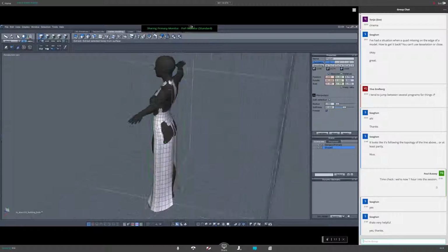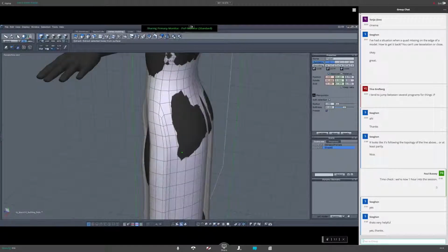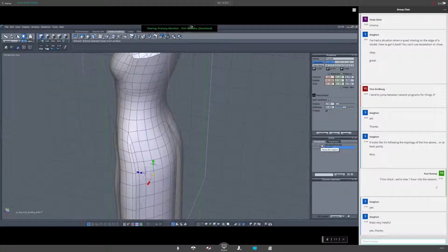And how do you do this without going crazy? Of course, symmetry is your friend. Select one of these offending polygons which have disappeared inside your figure and then use something called soft selection here. You see these red dots appearing around your selected polygon mean every polygon ringed with a red dot is going to be influenced by what I will do to this one.